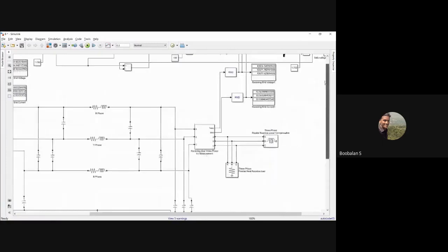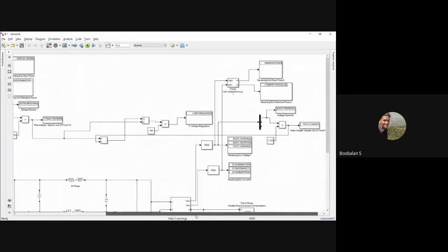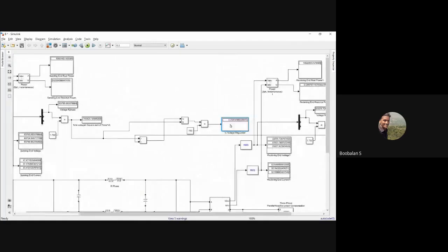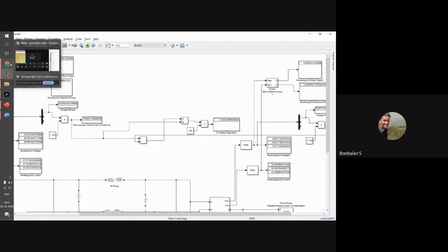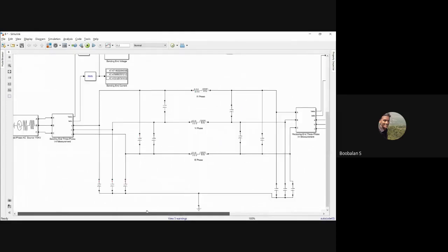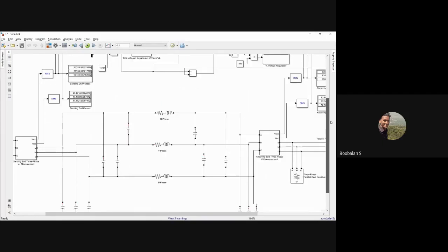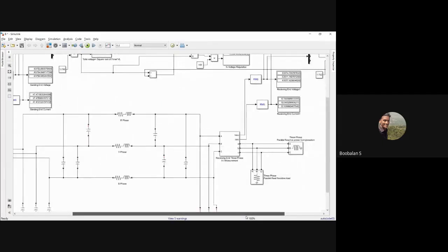And the final one is my transmission line power efficiency. What is the formula for calculating that? We have a simple formula: real power, that is receiving power divided by sending power, right? This is the output, this is my input. In my network, power efficiency is output by input, right? Efficiency is always the system's output divided by the system's input into 100. That's my efficiency: real power at my receiving end divided by real power at my sending end into 100.